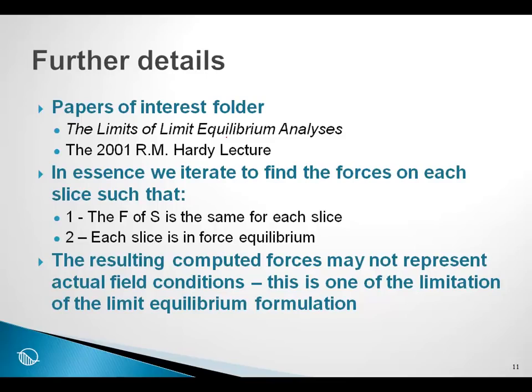In this paper there are two issues that are of extreme importance. At the root of the method, we in essence iterate to find the forces on each slice such that, one, the factor of safety is the same for each slice, and we find the forces on each slice such that each slice is in force equilibrium.